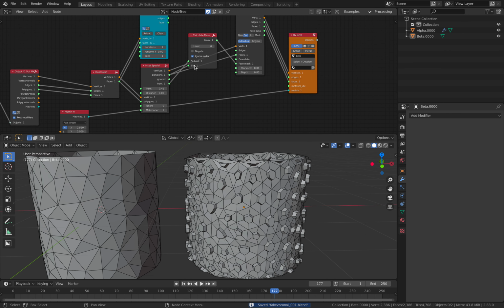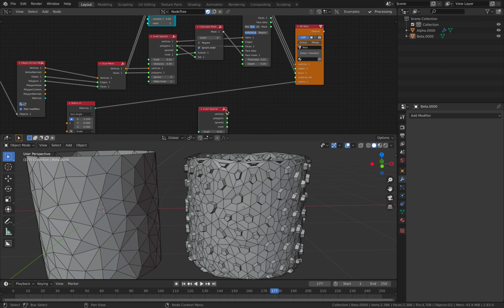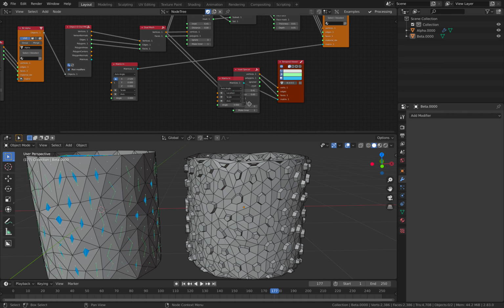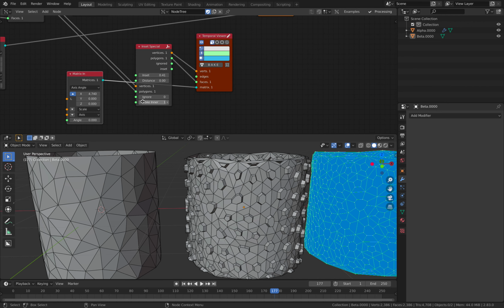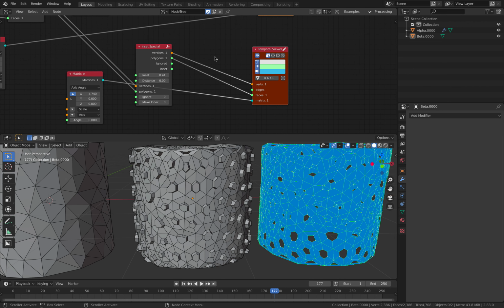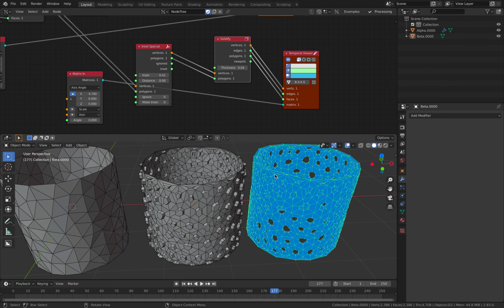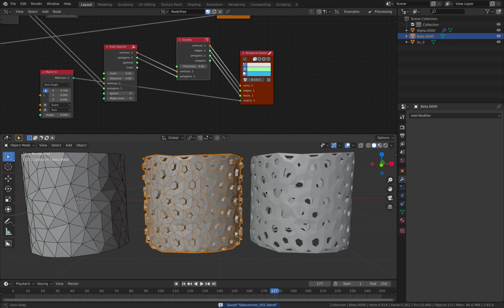And of course, if you really want, you can actually branch here. Use the dual mesh and use this instead. And then turn off the make inner. And here you can solidify. 1, 2, 3, tap V, thickness. So you can bake this, and you have this result.